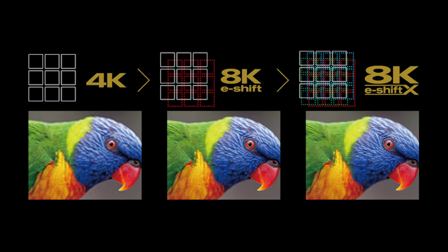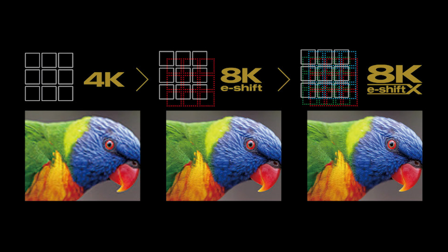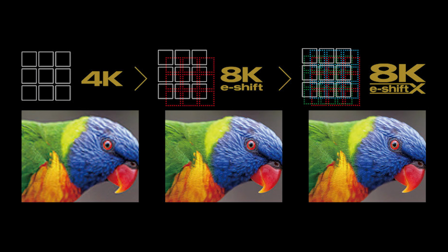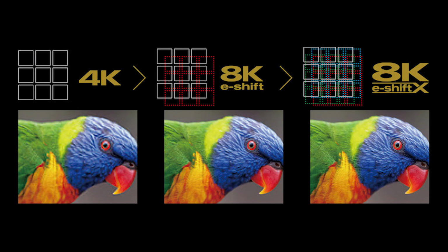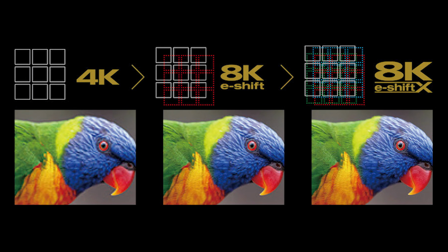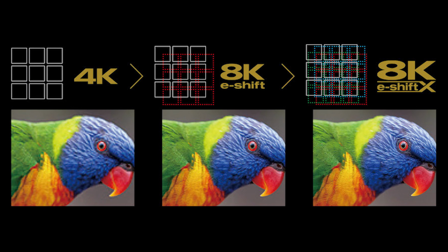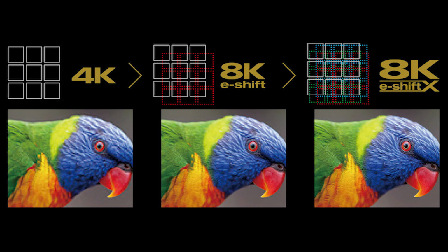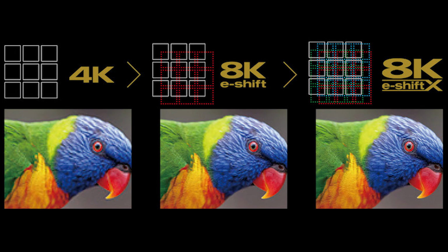Pixel shift technology is also used to obtain an 8K resolution viewing experience. For example, JVC offers 8K video projectors using its eShift technology. In this case, 3 native 4K LCOS-based D-ILA imaging chips are used as the starting point, and JVC's latest generation eShift process, called eShift X, is used to create the intended 8K display capability.